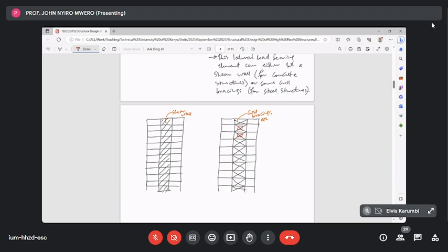There are ways of trying to hide them and to change the style a bit. You could do bracings, for example, in that manner, called the A bracing. Do them in that manner, so that then you can have space for the window, but it's still a hassle. So this would be done for structural steel structures mainly.